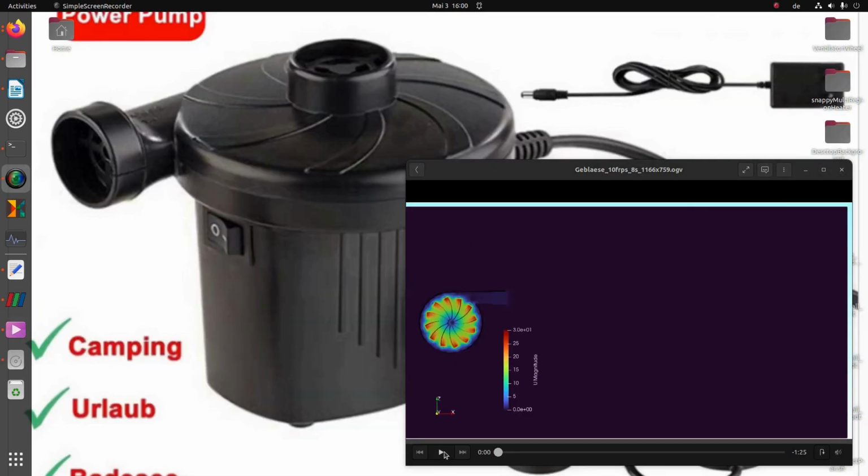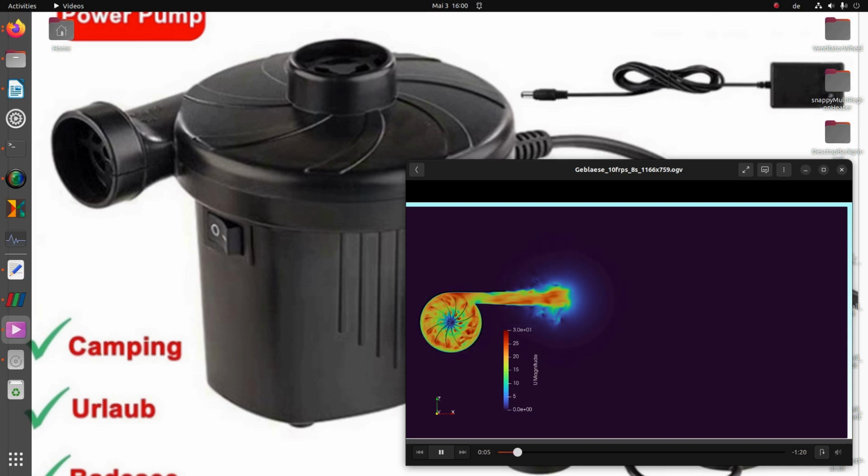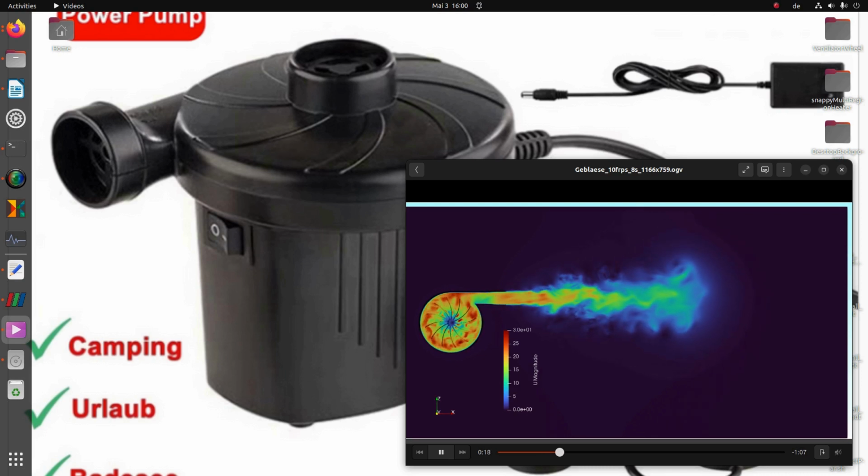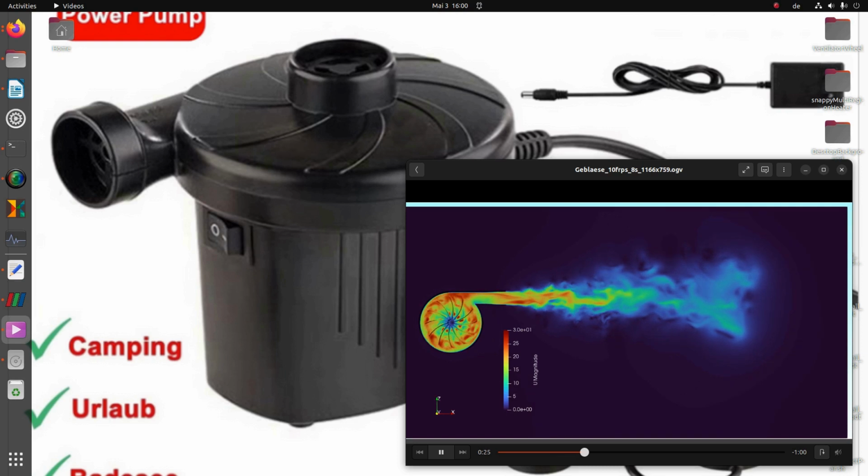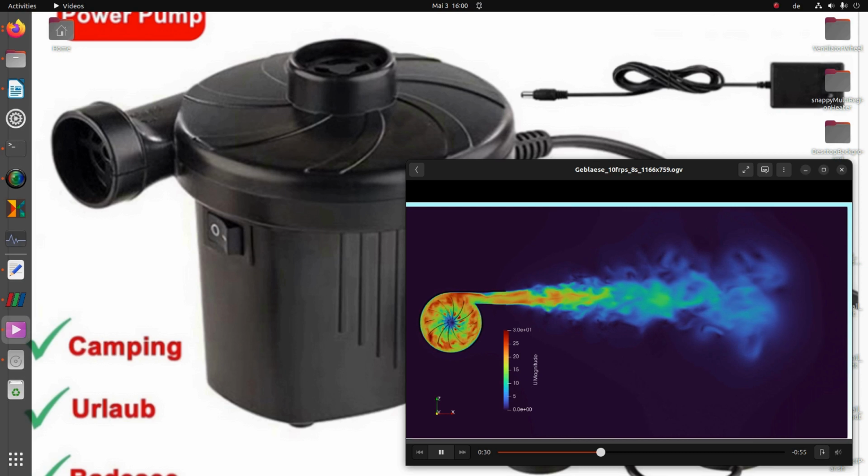Now we can make the summary. What we have learned in these 3 videos. First of all, we prepared the boundaries in Salome, defined the bounding box, selected the edge length according to the global cell size, and have done the definition of the refinement levels. We defined the snappyMeshDict and other dicts for the mesh using the preform template tool. Then we generated the block mesh and snappy mesh on the Linux computer.